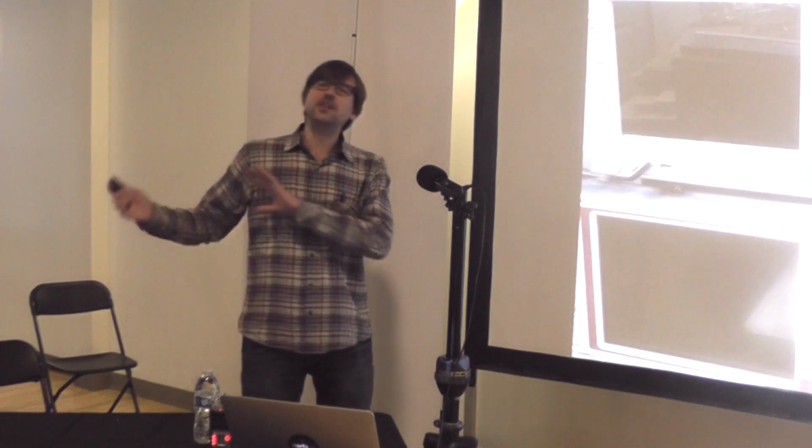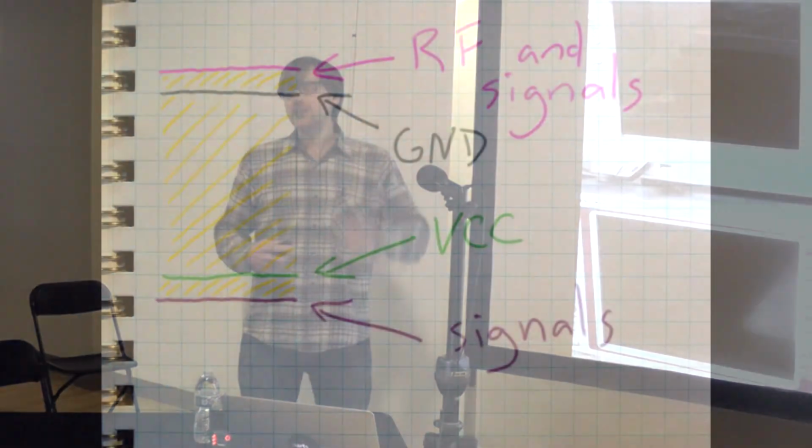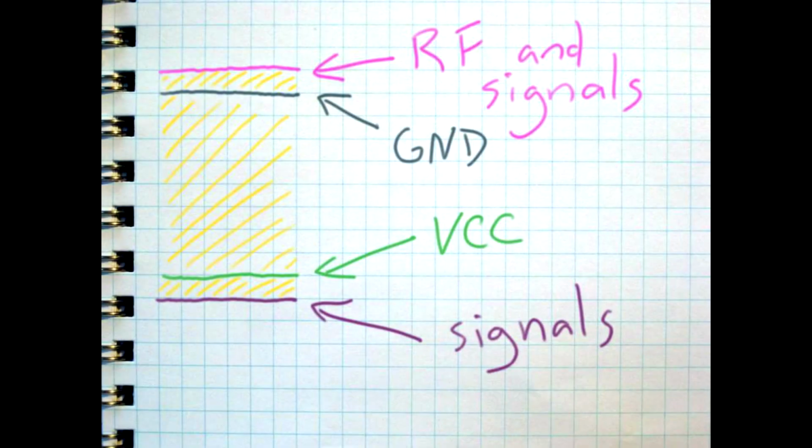We're not talking about that stuff that I consider advanced topics in RF circuits. So maybe you could get away with doing some 2-layer RF circuits. But the easy way is to go with 4 layers. Go with 4 layers, follow this type of stack up where you have a ground plane that is very close to your top layer, and you have your RF circuits, all your RF signals are on the top layer, and things will go so much easier for you. So that's rule number 1.